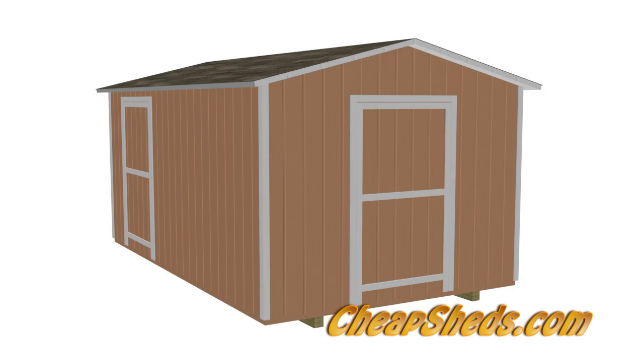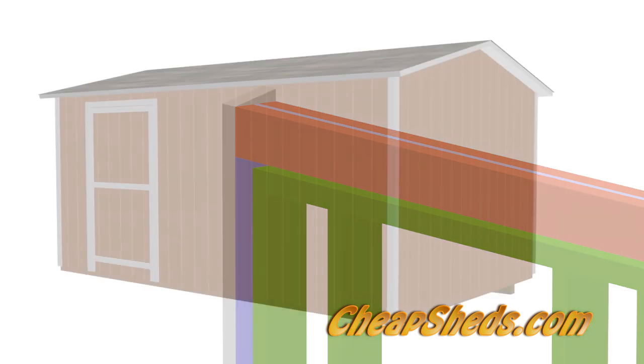The only difference between a side door and a door on the gable end is which king stud you will use. For a door in the gable end, use a square cut stud. For a door in a side wall, use a stud with an angle on it. If you're building the door in a side wall, remember to build with the short side of the angle up toward the siding. Otherwise, there is no difference in the construction.